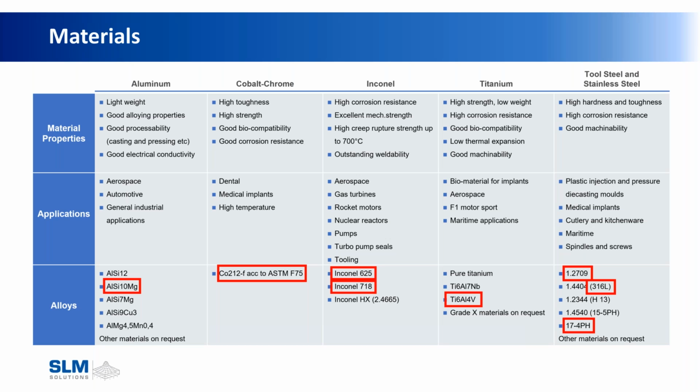That being said, additive was initially designed as a process around pre-established materials. So these are pretty established materials. Additive is reaching a point now where the material development is outpacing the machine development. So materials such as copper and new 6061 aluminums, other nickel-based space alloys, and titaniums are being introduced into the market and testing and working with this new additive process.